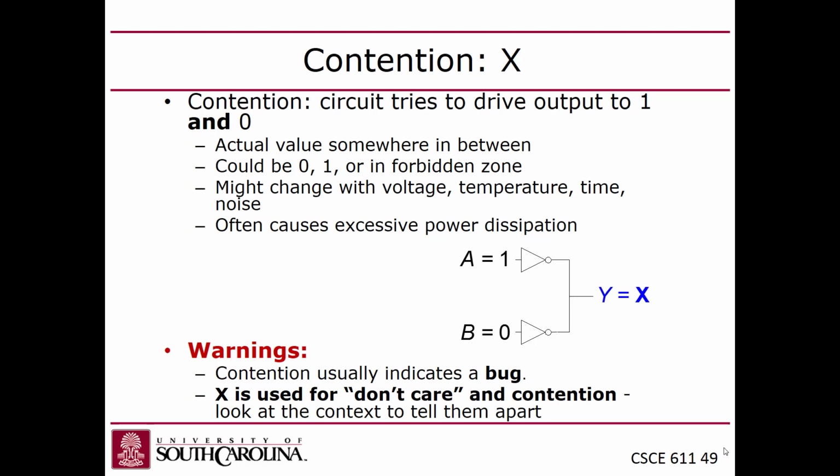And then finally, you can also use X when you actually set a signal as an X, as an output of a circuit, where you explicitly say X. That means it's a don't care output, right? So that's your way of telling the synthesizer tool, the compiler, that it can use that don't care to do some optimization, right? To minimize, to reduce the resource usage of the circuit potentially, right? Use that to its advantage in the optimization. You guys with me? Okay.